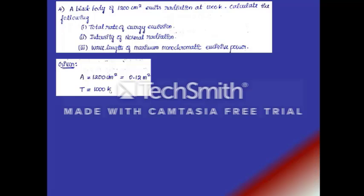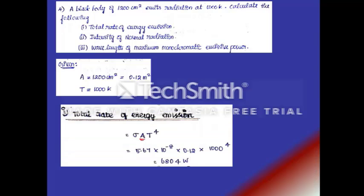What is the difference between emissive power or total emissive power and total rate of energy emission? Emissive power, as we have already seen, is defined as the amount of radiation emitted by a black body per unit time per unit area, so it is watts per meter square. Total rate of energy emission means the amount of radiation energy emitted by the body over its entire surface area. You multiply the emissive power by the surface area of the given body. That will give you the total rate of energy emission. Unit will be watts. Clear? So emissive power is energy per unit area. Rate of energy emission is simply energy, not per unit area. Our first job will be to find emissive power.